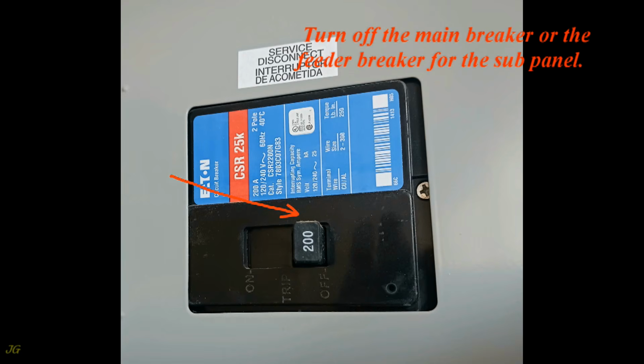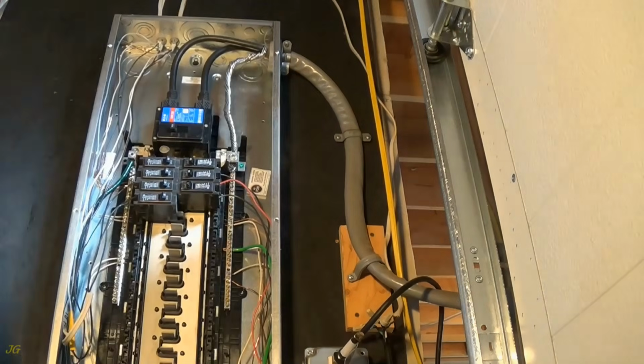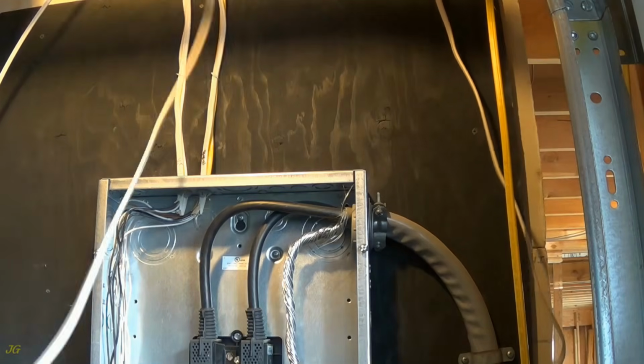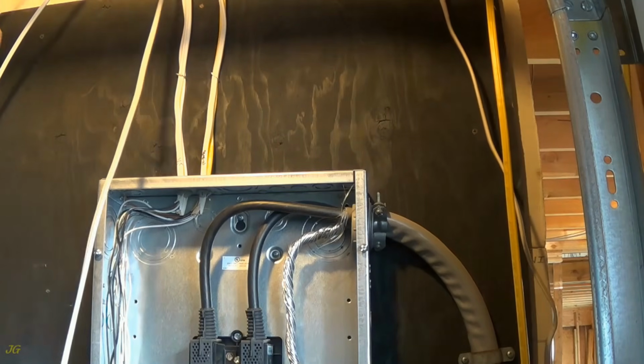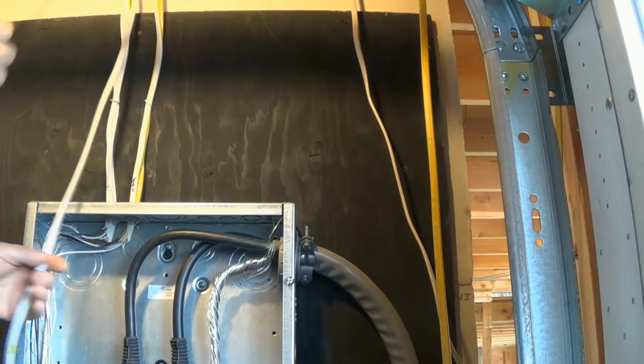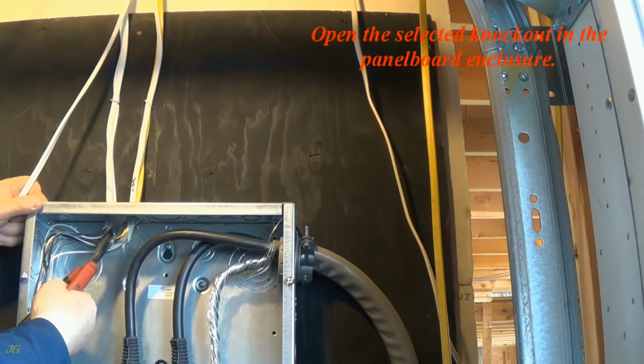Turn off the main breaker or the feeder breaker for the subpanel. Remove the panel cover. Open the selected knockout in the panel board enclosure.